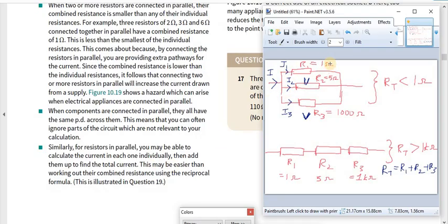So that is much easier than finding the total resistance here and then dividing V by that resistance, because to find this I, you can also use V equals IR. So if you are finding this I, another way to do it is I equals V over R. Now in this case, R will be R total. The potential difference across them is V, and the total current is I. So you have to imagine the total resistance of this part is RT.